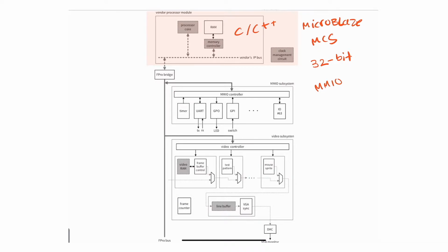And what you're going to see is we will be using what we call a MicroBlaze microcontroller system. As it turns out, there are different processors that we can incorporate. We can incorporate an ARM microcontroller or microprocessor or any other one, depending on which manufacturer or which FPGA manufacturer you're using. Since we're using Xilinx, we're going to be using the MicroBlaze microcontroller system. Xilinx provides another version, which is a MicroBlaze microprocessor. But we'll be doing the microcontroller system because it already has the components for the memory controller, the RAM, and everything. Within one single wizard, you can generate everything.